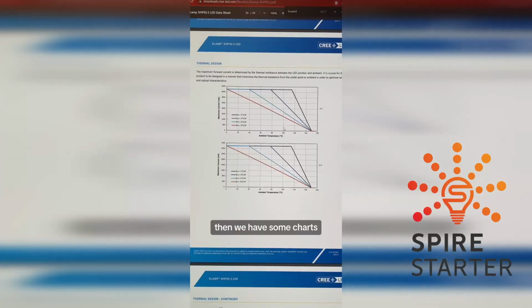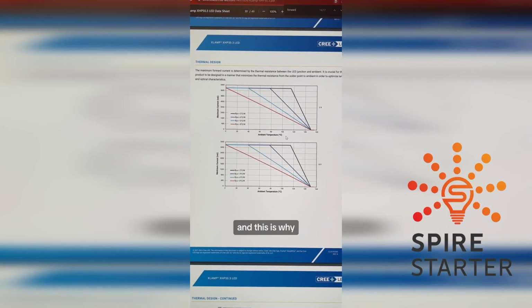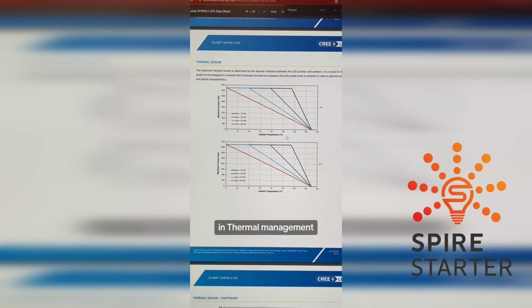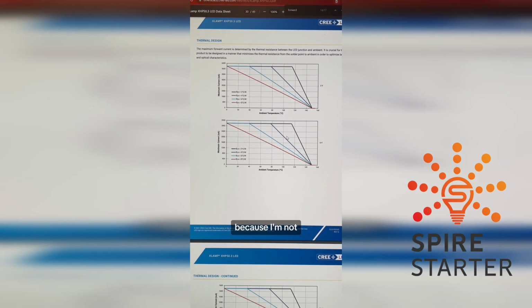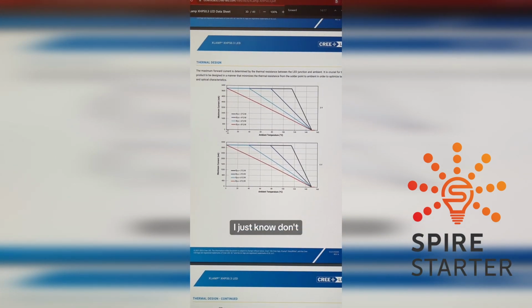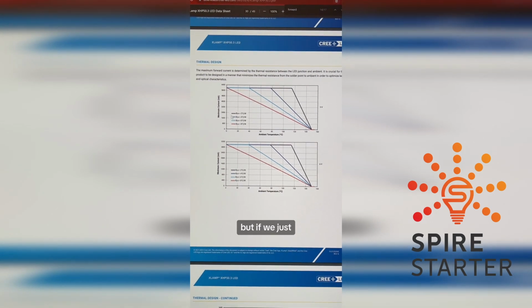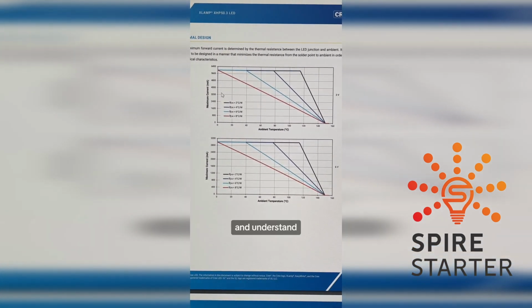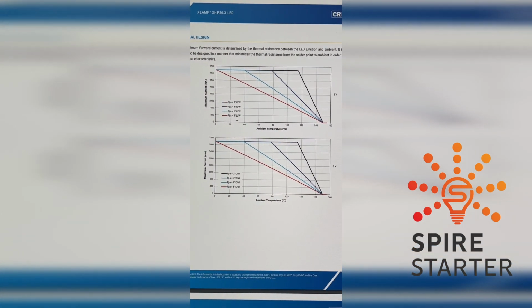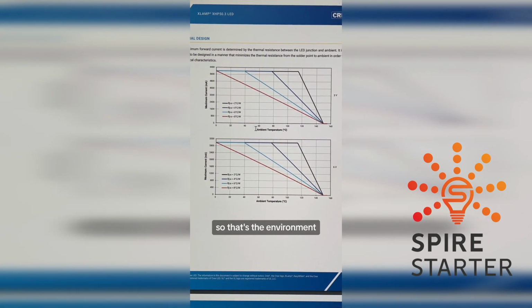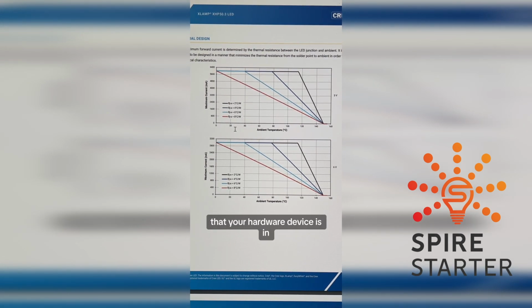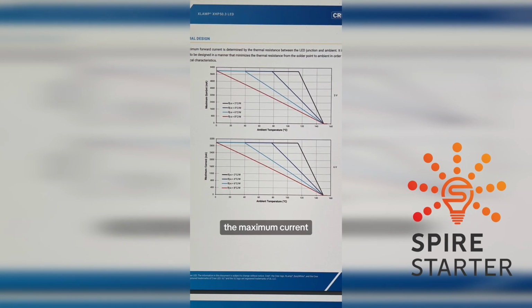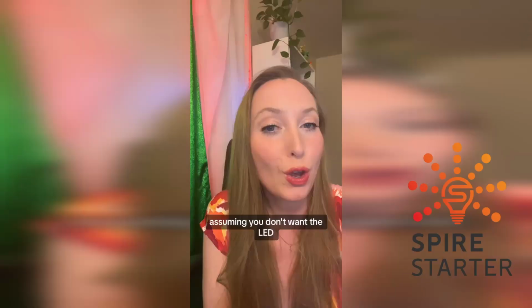You've been warned. Then we have some charts for thermal design, and this is why it's really great to have someone who's an expert in thermal management, because I'm not. I just know don't make it burn. But if we just try to read the chart and understand what it's saying, this is ambient temperature on the bottom. So that's the environment that your hardware device is in.